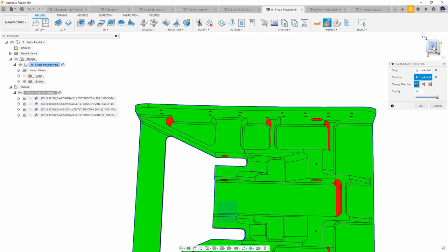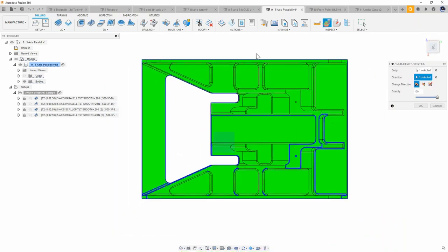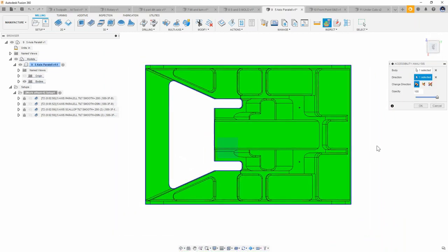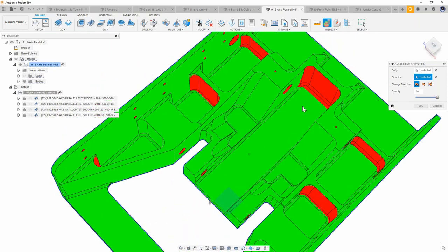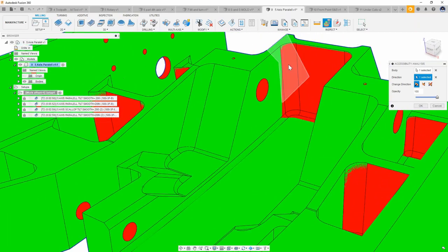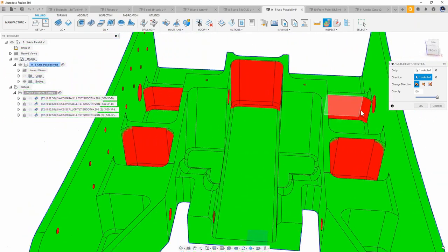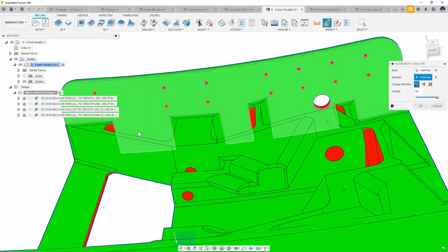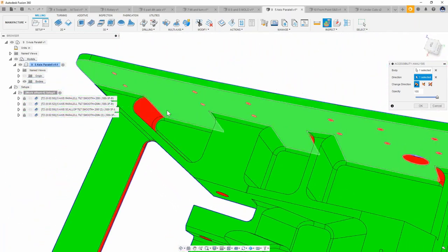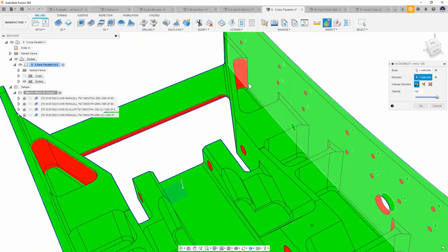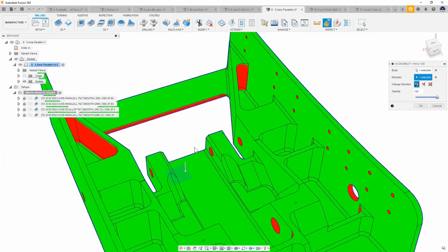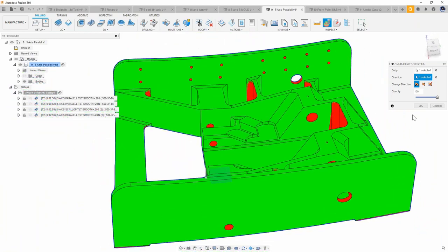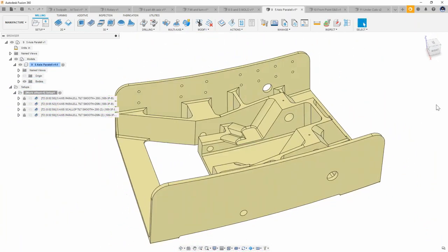And what that means is if I go to my top view here, I have this set to orthographic, and we can see that nothing here is displayed in red. But if I highlight one of these surfaces, you can see that the undercut here is pretty extreme, and it's in more than one location. So all these pockets here are normal to the floor of the surface here, and then even these front cavities, which was a really big pain in the butt for me to make the first time. So let's look at how we could fix this.